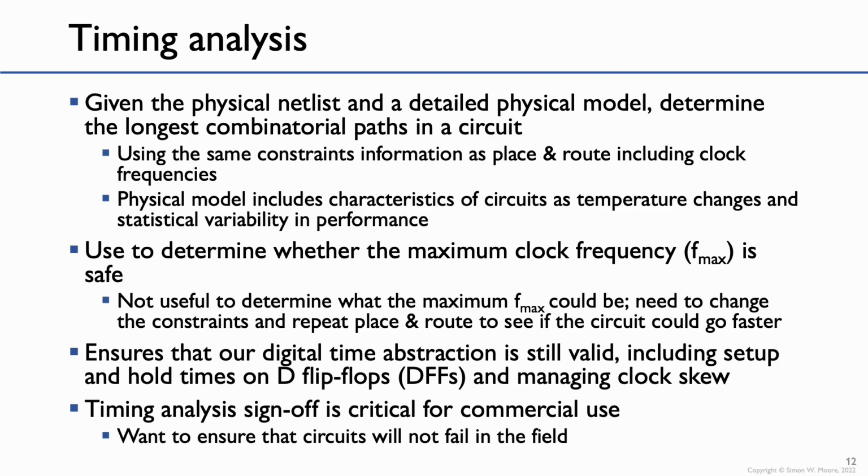So once we've actually analysed the design and ensured that the setup and hold times are met for our D flip-flops, that then determines whether the circuit will work correctly in the field. And so this timing sign-off is absolutely critical, and the tools you're using in the lab are commercial tools, and for commercial customers, the provider of those tools is willing to sign off on the numbers.